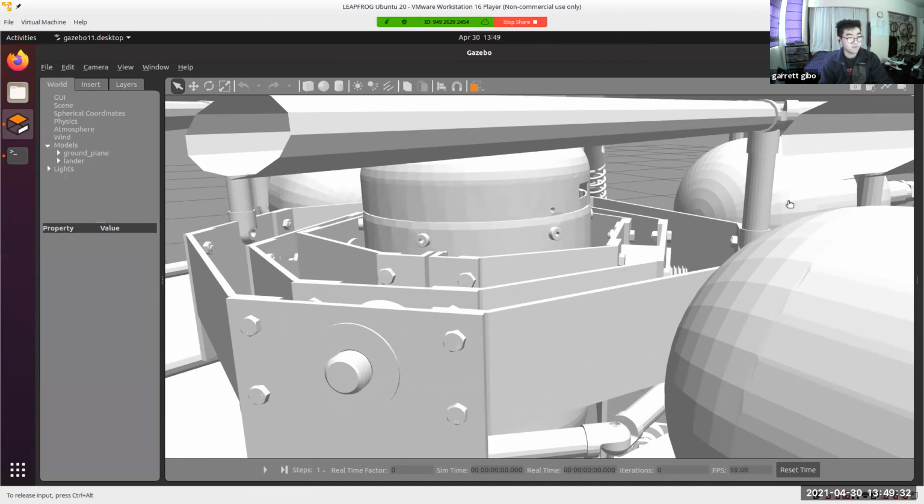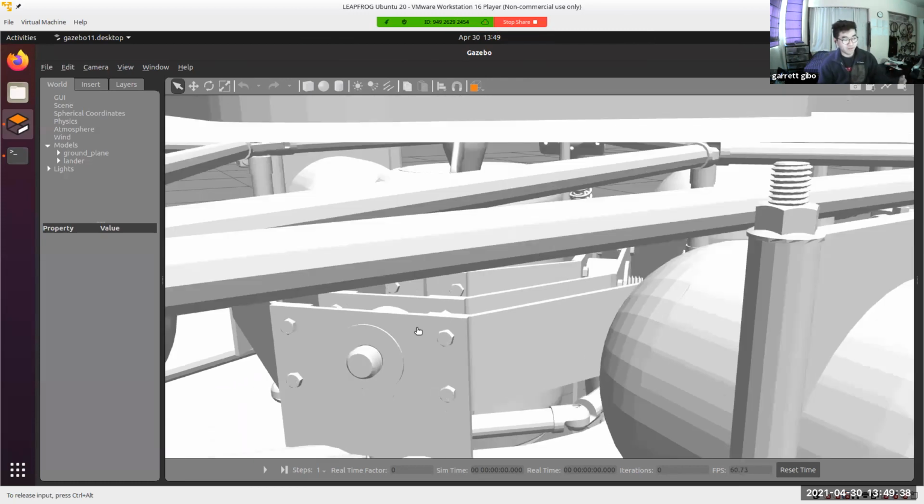I'm going to go over how to use Gazebo a little bit here. So I've been navigating around this and manually inspecting it, which is possible for me right now because I launched this environment world in paused mode by default. Gazebo allows you to control the time of the simulation manually. And right now when I'm launching it, it's paused. So if I pressed play, it would start the simulation, start the physics engine, and try to start simulating things. If you want to do it very slowly, then you can just step forward one step at a time and view the behavior that way. You can also control the speed of the world to increase or decrease the time if that helps you in your debugging process.